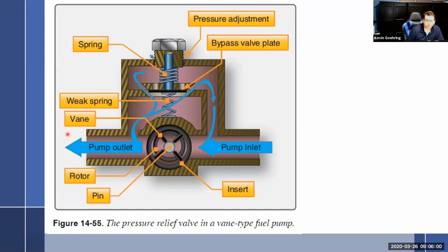And they only really work well off the engine-driven pump. It's part of their design. But we get this thing off and running, and like any good pump, it really needs to put out more than the fuel control unit uses. It would be very difficult to design something that only created just the exact amount that's needed, not a bit more. And then of course, once it starts wearing because it gets older, then it's going to be insufficient. So we have to have some sort of pressure relief valve.